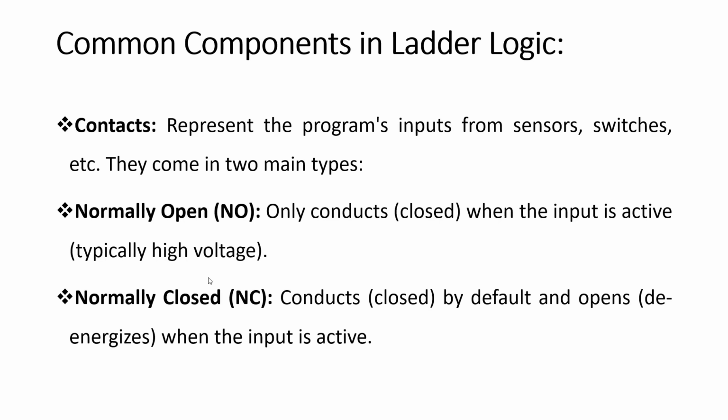For example, with motors, it is a common practice to put the start push button in a normally open position, while the stop or emergency stop buttons or push buttons are always connected normally closed.